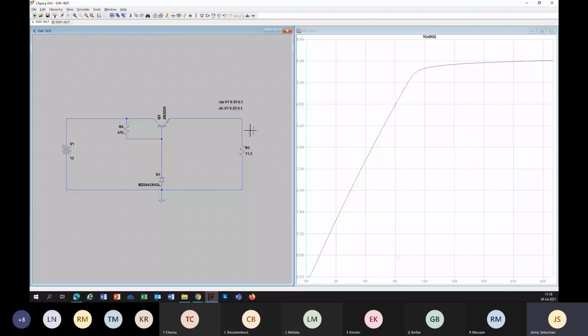Okay, now we can also check the Zener diode voltage. This voltage is supposed to stay constant. Let us see. That is the Zener diode voltage. It is supposed to remain constant, but you can see it is not. When the input is around 12 volt, output voltage is 6.2. When the input incremented, output is also incrementing, even though it is not heavily incremented. Okay, so this is not a perfect series voltage regulator.